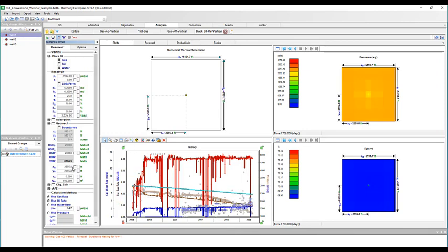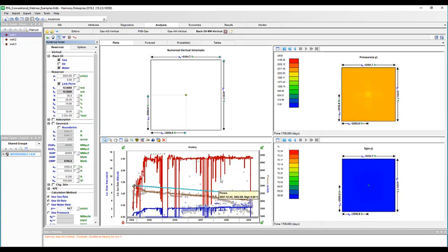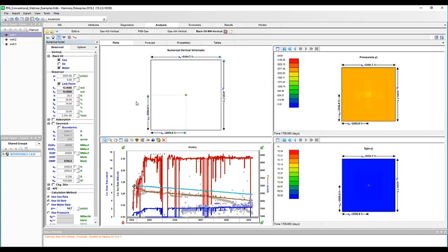You can see that automatically using those parameters from the analytical model, it's not given me a great history match. I can start to change specific parameters manually to see how that will help me gain a better history match. So if I increase my permeability to around about 10 millidarcy, we can see that that's actually given me a much better history match. We have that falling off due to the interference effect, so the latter part of the data doesn't match.